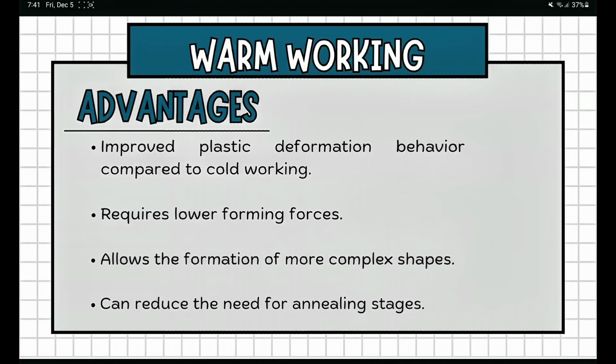So for the advantages of warm working, the first one is improved plastic deformation behavior compared to cold working. At warm temperatures, the metal becomes more flexible and easier to shape. This reduces the risk of cracking during formation.